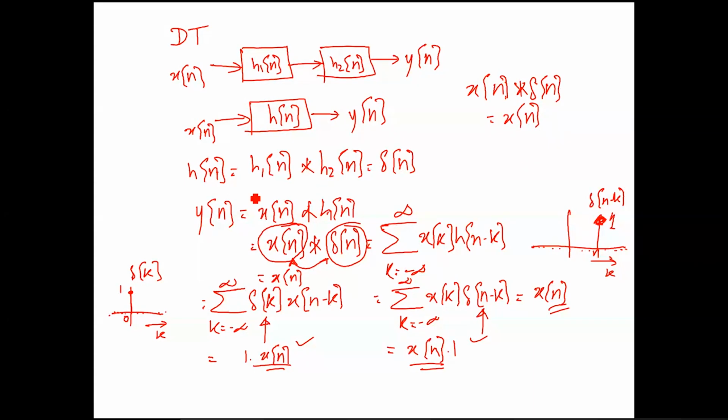First of all, any confusions right here? We just showed you that convolution of anything with delta n, the unit impulse, ends up giving us the same thing back. And this actually led us to another thing inside summation. If you end up getting this impulse, then it simplifies the whole summation, because this whole product will have just one value. You can just see that summation and directly write the answer.